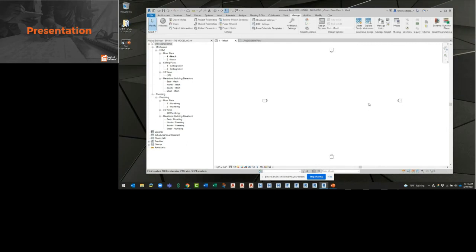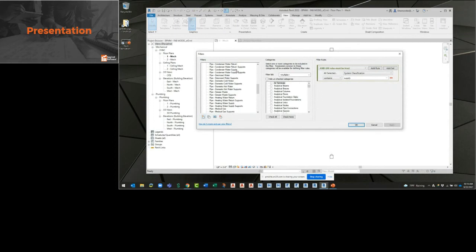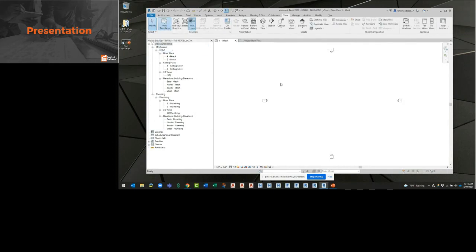And this is kind of like AutoCAD, if you're doing the content browser and you're just bringing styles over. It's just exactly what I did there. I brought some information over into this project. And on the View tab here is where you can manage those filters. Those will all be in here now, new ones, and then my View templates as well.